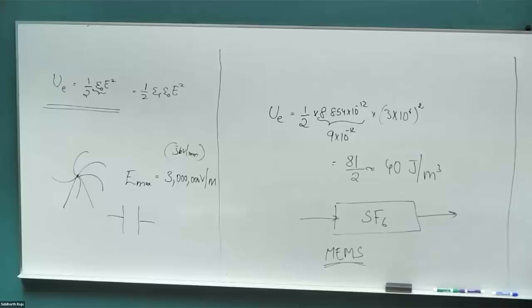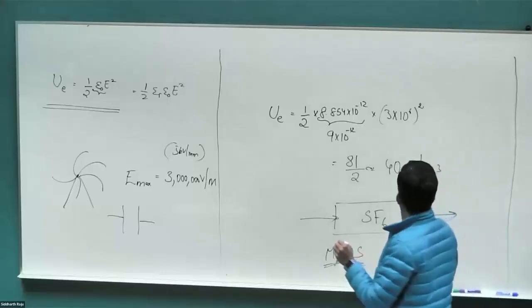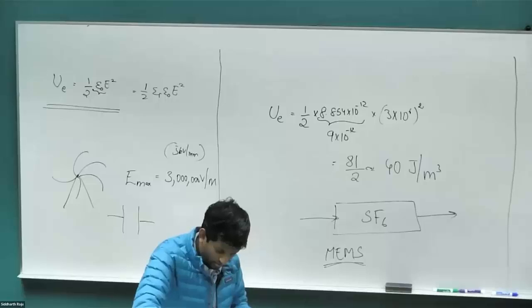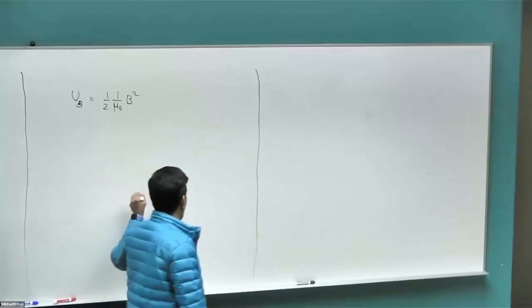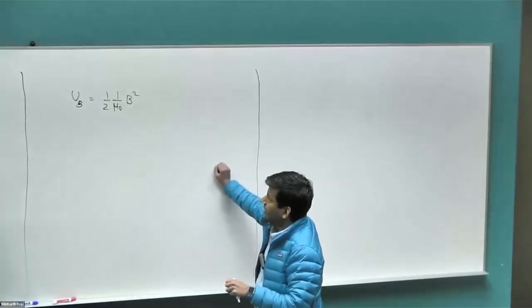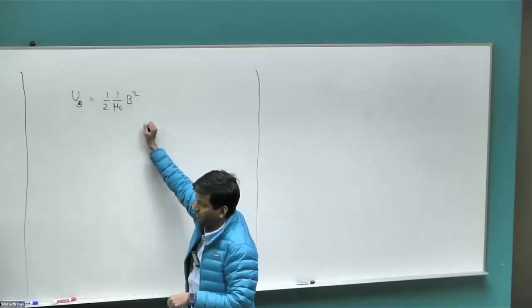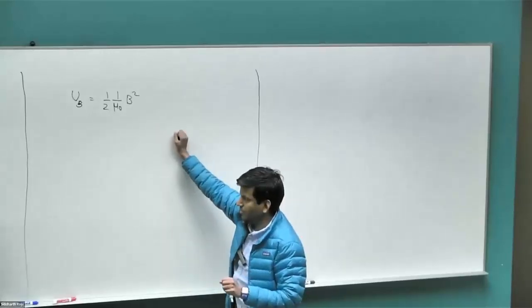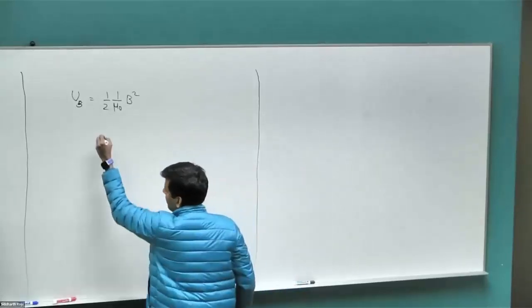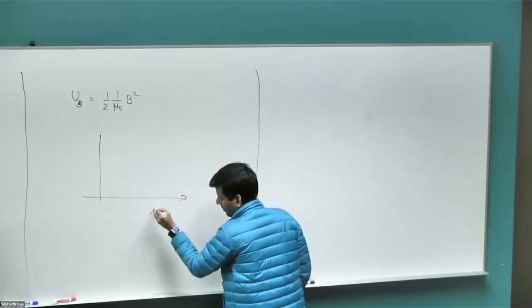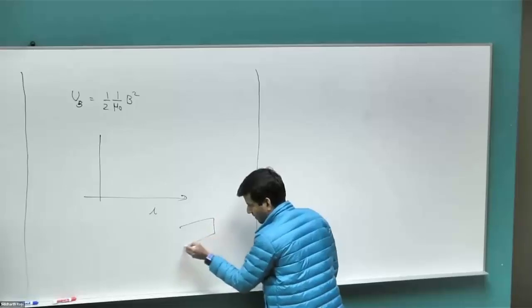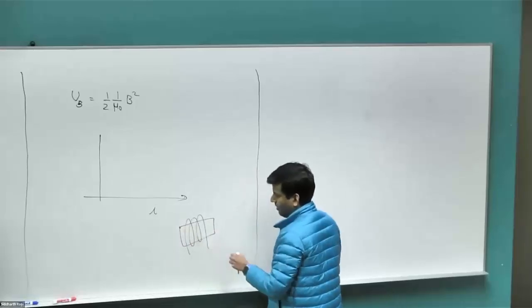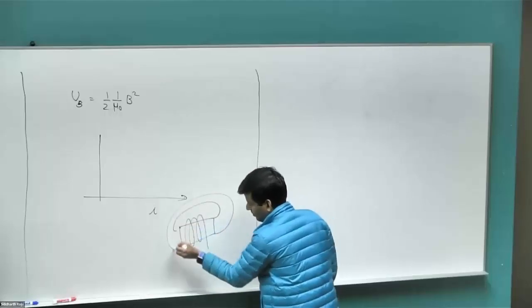And if you look at these motors that we have here, in the case of air, we have a limitation in the electric field where, if you go above it, the medium is going to start to puncture. In the case of a motor, we have a similar limitation, but it's not that the material is going to puncture, the material is rather going to saturate. We'll look at the theory of how it saturates later, but for now, just think of it like this. Take an iron bar, wind it with some coil, right? A closed iron bar, a toroid of some sort.